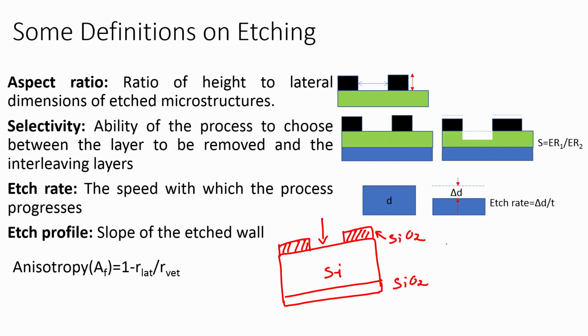We know that for etching silicon using wet chemical etching, we have potassium hydroxide and we have TMAH, right. And if you remember, with potassium hydroxide we perform etching at 80 degree centigrade, TMAH at 25 degree centigrade. KOH is faster etching, TMAH is slower etching.